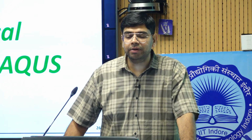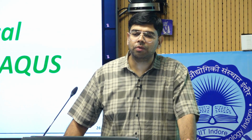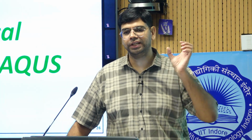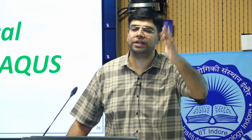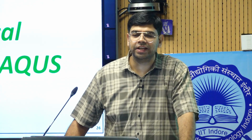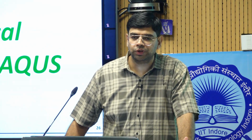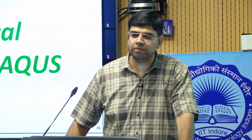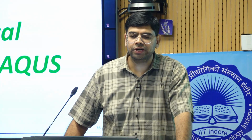But in the finite element method, which is a numerical technique, there is an option, so you can incorporate the inhomogeneous deformation. In inhomogeneous deformation, your tangent modulus comes into the picture. Your modulus is going to vary throughout the active area of the membrane that we are considering. So FEM provides a suitable tool, or a platform, by which we can incorporate inhomogeneous deformation. That is one advantage.